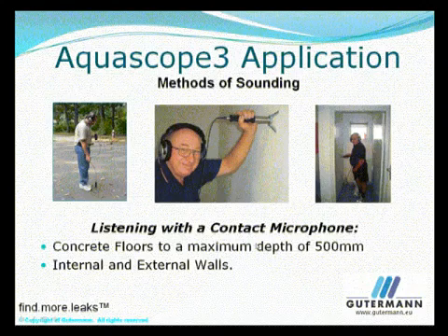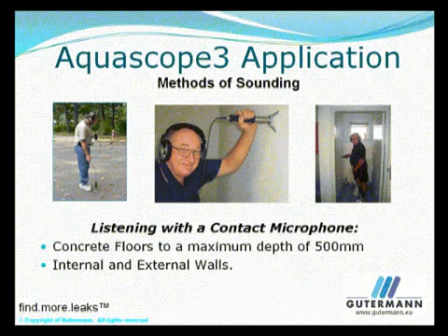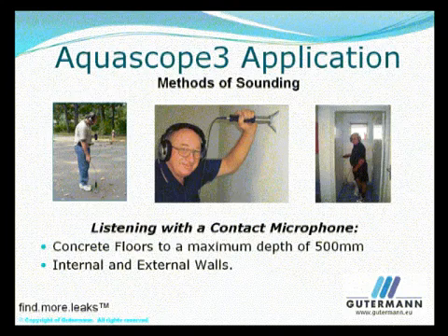The leak position can be pinpointed using the tripod foot when the leak position is a wall, under concrete slab, or when it's buried in pipe underground at a depth of 500 millimeters or less. The tripod foot is the best way of finding leaks under a concrete slab because the ground microphone is often too powerful.